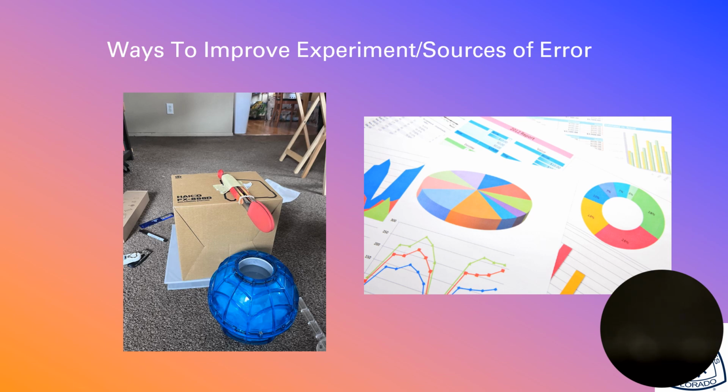The temperature of the room fluctuated due to the outside temperature decreasing and also the house furnace increasing the inside temperature. The velocity of the air that was measured likely also changed from the velocity during the actual experiment, and the velocity of the air during the experiment likely fluctuated over time due to inconsistent air flow from the fan and movement around the project. Along with this, the assumption of an adiabatic fin tip may have also introduced errors into the analysis.